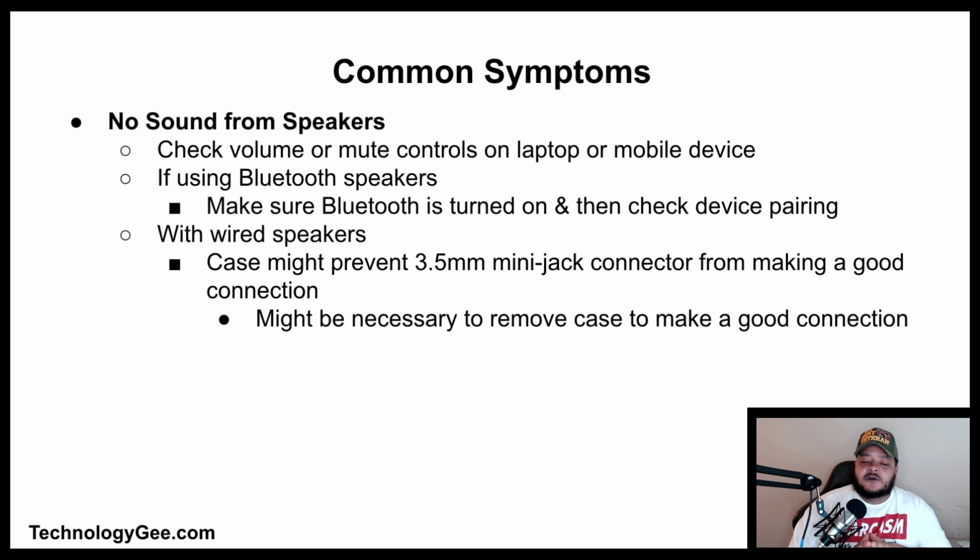If you have no sound coming from the speakers, this can cause several issues. You need to check the volume or mute controls on the laptop or the mobile device. If you're using Bluetooth speakers, you need to make sure that the Bluetooth is turned on, and then check the device pairing. With wired speakers, the case might prevent the 3.5mm mini jack connector from making a good connection. It may be necessary to remove the case so that you can establish a good connection.